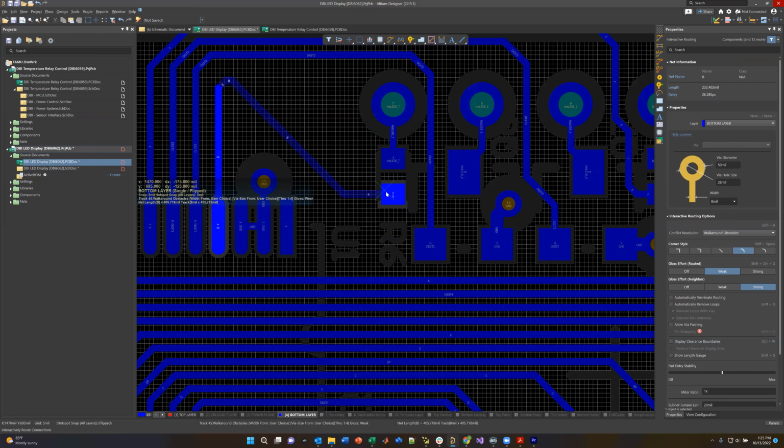Basically, that was manually routed by me. I did not use an auto router for that. So just put it back the way it was. So notice the nets have got all their labels, so we know exactly what it is. This is net A, digit 4, E, D, decimal point, so on and so forth. So that is kind of the general routing concept.